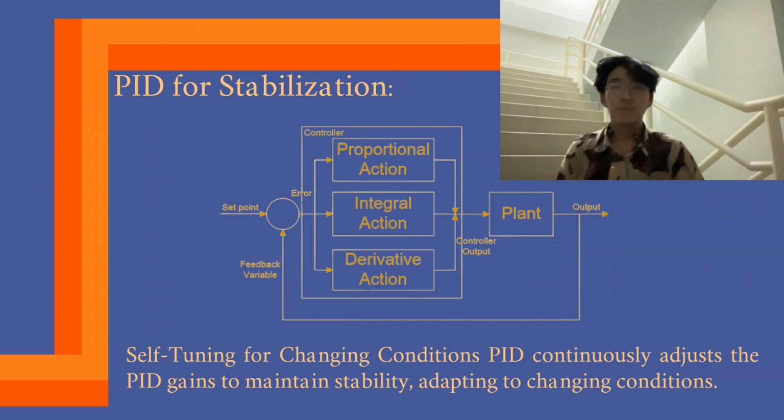monitoring the error between what the control system wants and what the value of the control system actually is. And in the following you can see a block diagram, and I'm going to try to simplify the main 3 points of the block diagram, which are the proportional, integral, and the derivative. So the proportional term provides basically an immediate response to the current error, and whatever error there is, it adjusts the system based on the magnitude of the error.